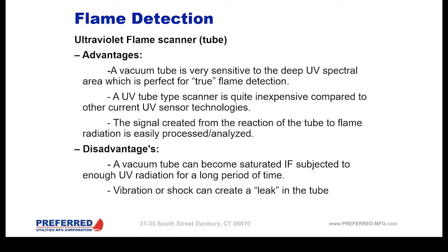It still works extremely well. As we mentioned, you need to use self-check where it's necessary. But other than that, it's just still a really good, reliable way of sensing combustion, true combustion. The signal created from that reaction in the tube itself is also very easily processed and analyzed. So it's a technology that quite honestly hasn't changed dramatically in decades, but it's still extremely viable.